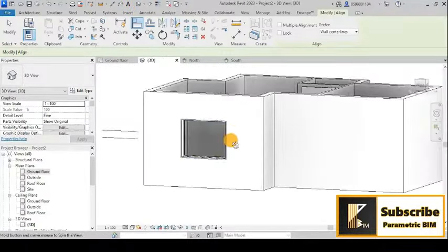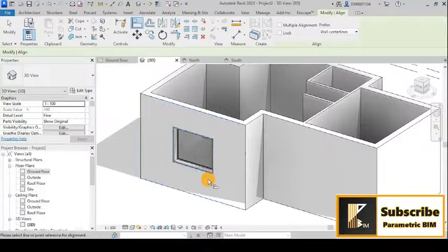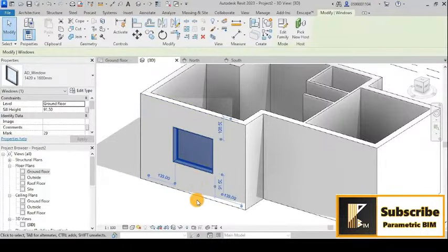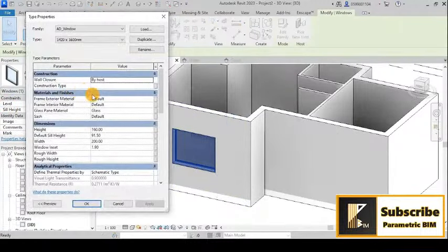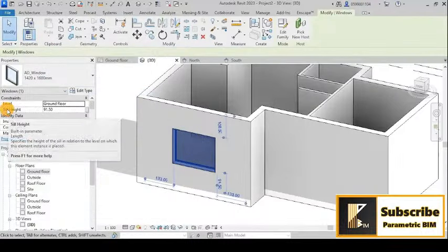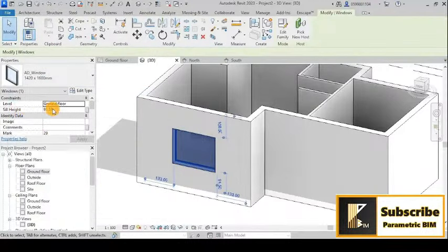In this wall. Also, the sill height is a very important topic to talk about. So the default sill height here for the family is 21.5, but you can also change it for all the type, or you have the opportunity, as this is an instance parameter, to change just this window.